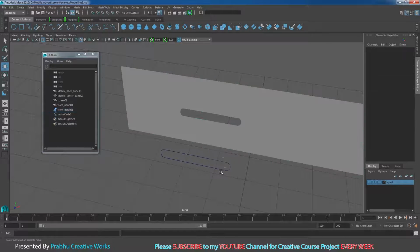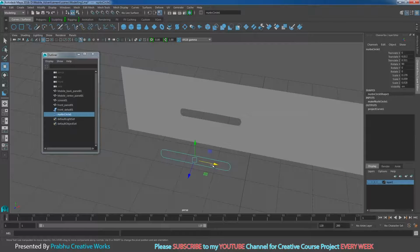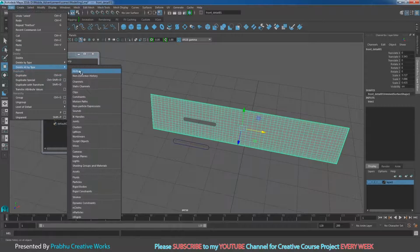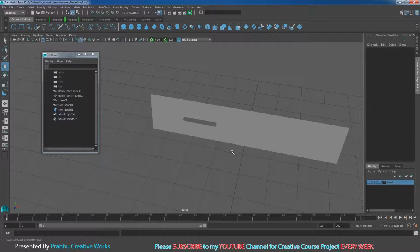Now I want to delete this node circle. So before that you want to clear the history, otherwise when I move, the hole will be followed. So I will undo that one. So select this object, go to edit, delete by type and choose history. So now I select my node circle and press delete on the keyboard.